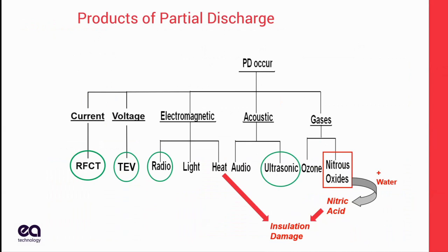The first effect I'm going to talk about is heat. Now, partial discharge is a very low energy event. It does not involve a lot of watts, so you don't have a big heat impact, but it is a very high temperature. So those are not diametrically opposed. It's plasma. It's very hot. By its definition, plasma is in thousands of degrees, but there's not a lot of caloric energy in there. So what you get is local to it, you might damage the insulation. A couple molecules of insulation maybe on each spark get damaged. It's slow moving, but that heat is going to damage the insulation.